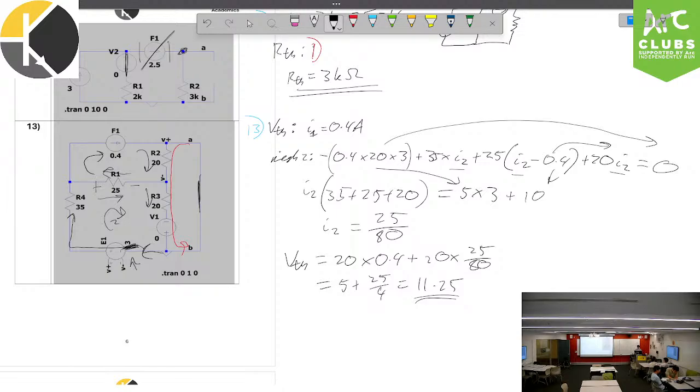Now, the funny thing with this mesh is there is absolutely nothing driving it. There's absolutely nothing driving it. And what I mean by that is there's no voltage source. I can have currents, but those currents are typically going to be net from the other sides. So what am I going to do? Well, I just make another mesh equation, I3, okay?